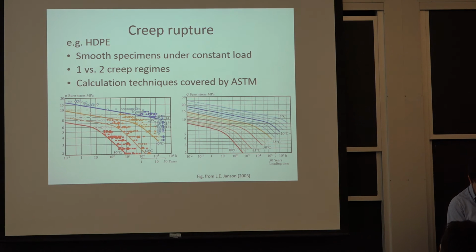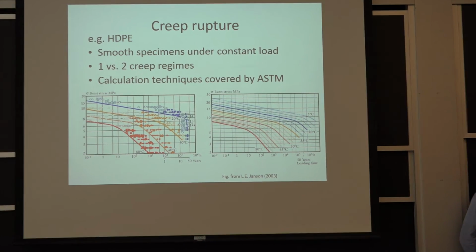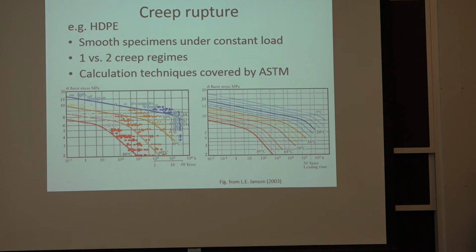All right. So what's the problem with plastics, guys? Why are we not using them all the time for everything? Tell me. It's not price, by the way. Yes. It will deform. So if you're thinking about a long-term load, like the pressure in a pipe, the weight of a building, I mean, everything, essentially, the frame of a car, it's a sustained load or a repeated load, and that causes the material to creep.